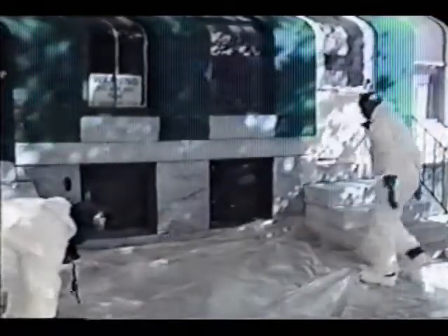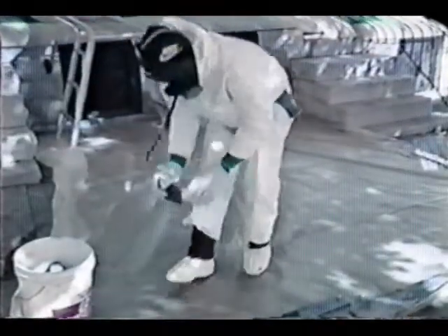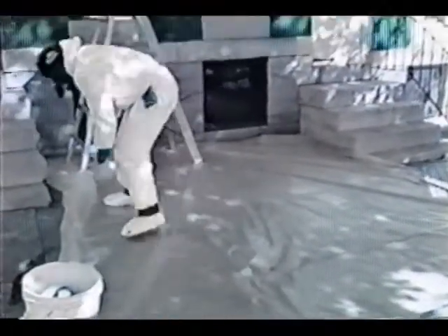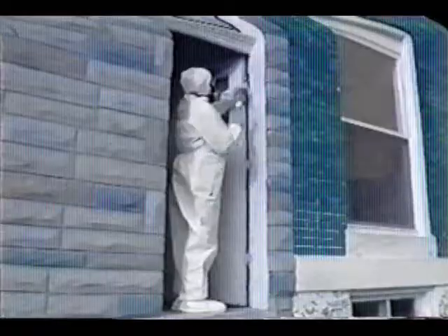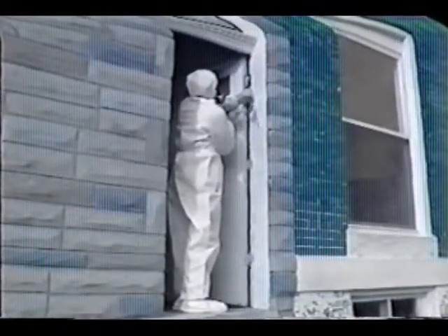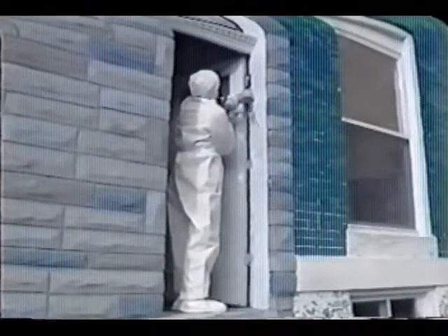If exterior abatement will be conducted, the area immediately beneath the work surfaces should be protected with plastic. Plastic sheeting should be extended 10 feet from the wall and should be weighted down so that it does not blow in the wind. Exterior plastic should not be left down overnight or during inclement weather. Once the work site is prepared, the dwelling unit is ready for the hazard control work to begin.